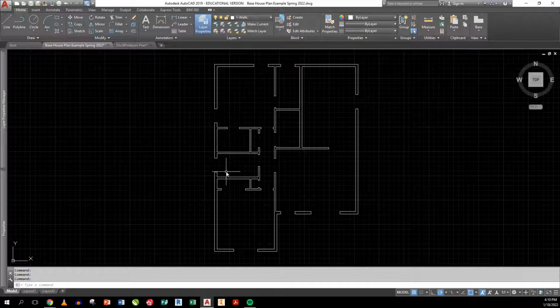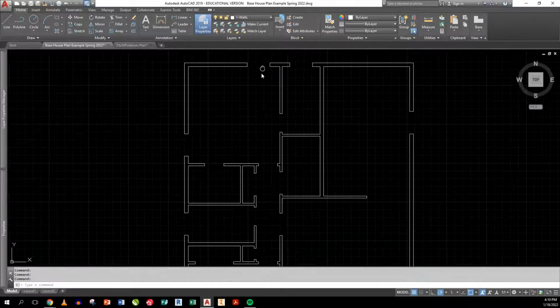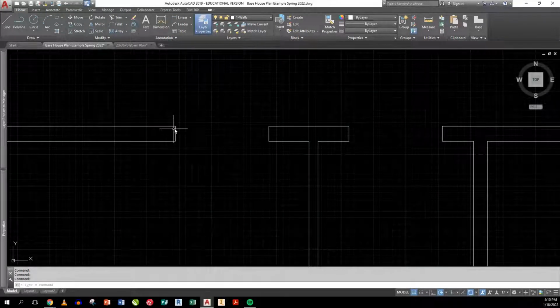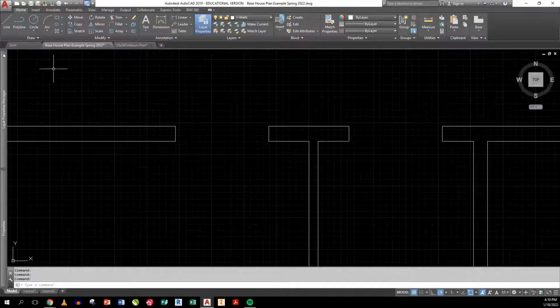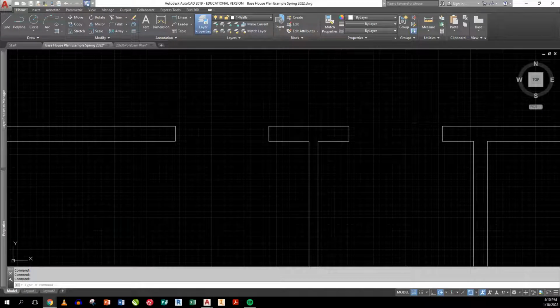Now I've cut all my window openings, but I haven't actually made a window in this. So I'm going to zoom in. We'll pick this one right here. Now this is a 3.0, I think 5.0 window. Let me double check on our sketch. Pardon me, it's a 3.0, 4.0 window. So it's 3 feet wide, 4 feet tall, and it's a vertical slider because it's taller than it is wide. That means the bottom half of the window opens up 3 feet wide by 2 feet tall. When you slide it up, it meets secondary egress requirements.